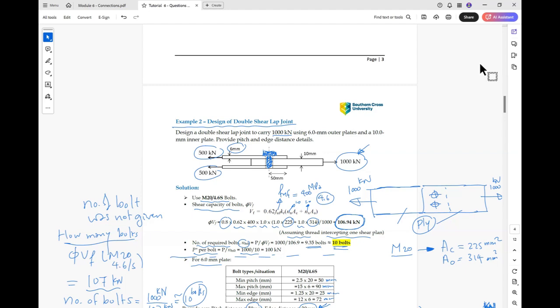So we don't need to do the load combinations, like factoring in 1.2 G plus 1.5 Q plus W? Yes, this would be the load combination on the rafter. And because the column has only wind load, it will stay at 2.